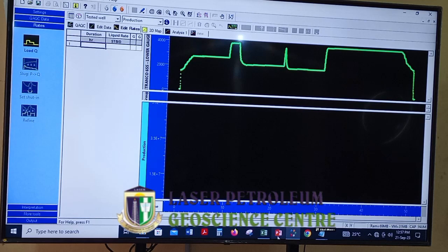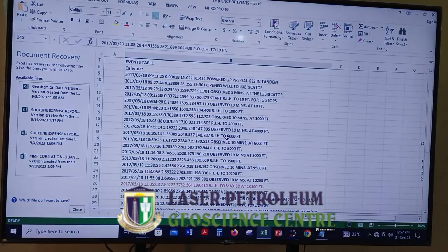So we're going to do the calculation on paper. Write it like that for me: Drawdown 1, Drawdown 2, Drawdown 3, Buildup 1, Buildup 2, Buildup 3. That's what we use to fill that Edit Rate. But where to get the information is in the wireline man's report.